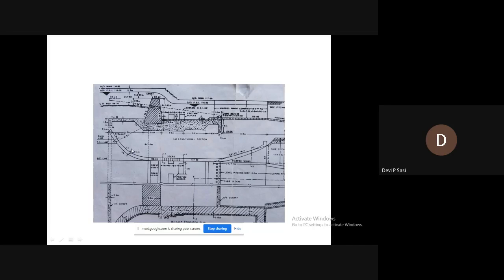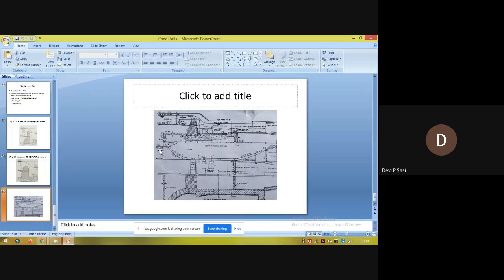This is the upstream wing, and this segment is the downstream wing. So the downstream protection consists of downstream bed pitching, side pitching, downstream wings and energy dissipators. And these are the energy dissipators. There are several friction blocks and Q blocks you can see in the figure.